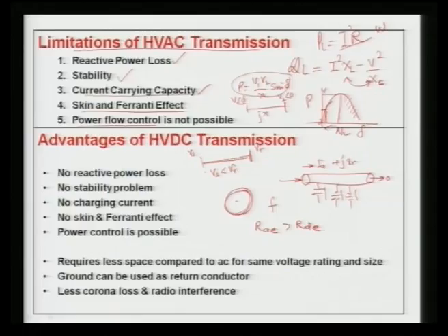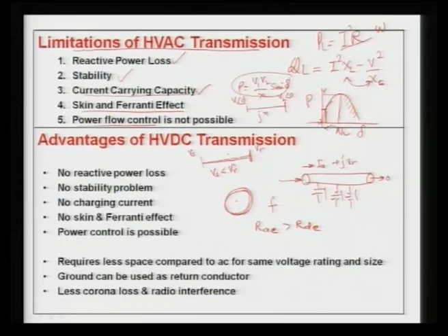So, what we do, we go for various mechanisms to limit this voltage, especially if you are charging the line, there is no load, and then the high voltage will be there at this end, and there will be again the tripping of the system. So, we put various reactors: we put line reactors if the line is very long, and then if you still require more reactive power, you can put a bus reactor, and sometimes we also use tertiary reactors as well.